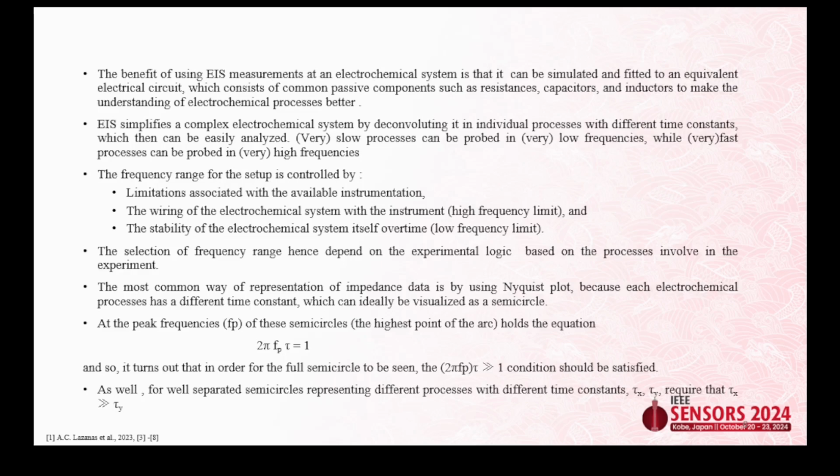So before we schedule our EIS measurement, these are some of the components that we try to understand, that these components should be there. Before I take the measurement, I should know my frequency range, and there is no single theoretical measurement which can tell us that this frequency range is going to be the best range for my measurement. So we have to trial and run and understand in which range or which kind of passive element is going to occur in my process, so that I can use the frequency based upon that.